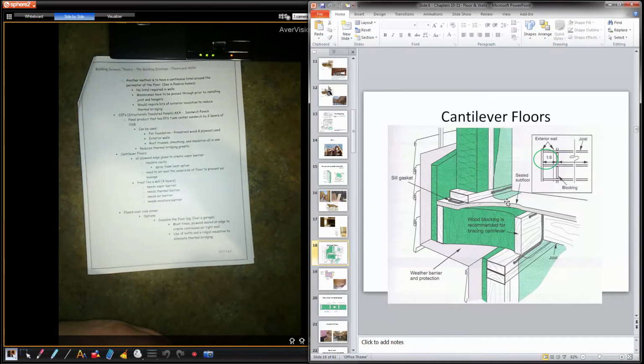And then let's say you go put hardwood flooring on top of that plywood. Every time you put a staple through the hardwood flooring, it punctures through the plywood, and then it would puncture through the 6mm poly. Well, the 6mm poly is not fully attached to the plywood, so it could go down by pressure and have air leakage through those staple holes. You can see right here too, sealed subfloor. All the joints are glued, and you're gluing the plywood to the floor. Okay, so that's going to be your vapor.